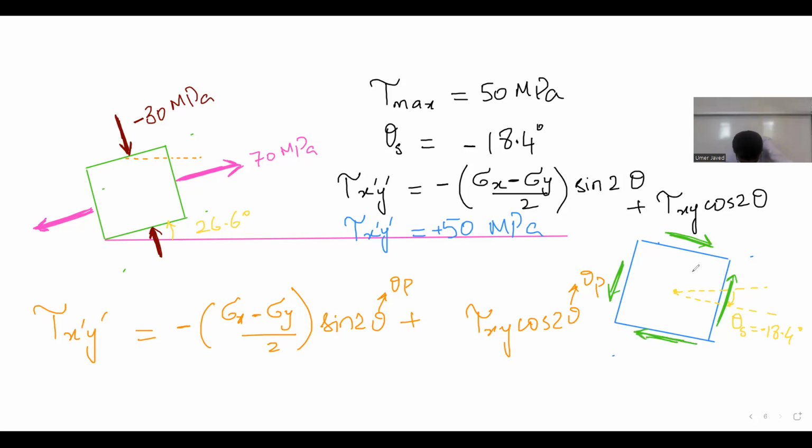Okay, now one last question for all of you. What will be the principal stresses over this? Any student? Zero. Not principal. I formulated the question incorrectly. Please pardon me. I meant normal stresses. Why would I talk about principal stresses? Principal stresses lie on planes which don't have any shear stress. The plane on which I have maximum shear stress, please give me the normal stress, not principal stress, pardon me. Give me the normal stress.